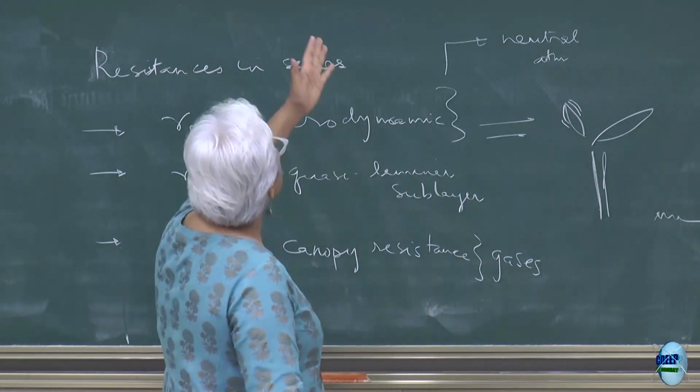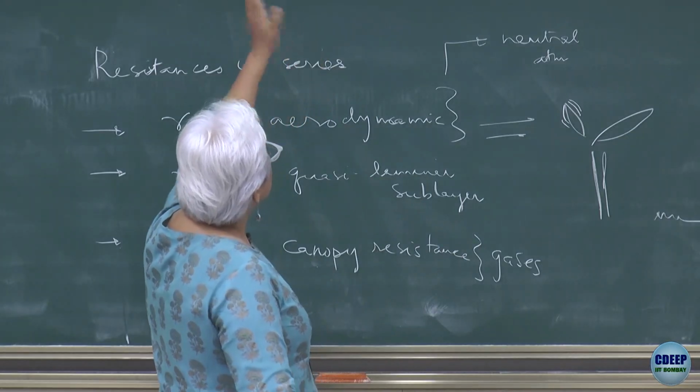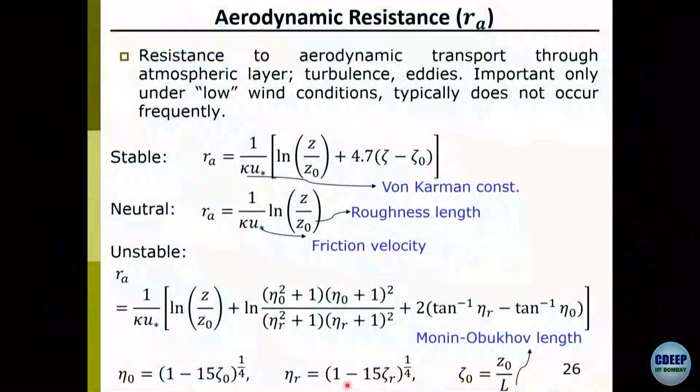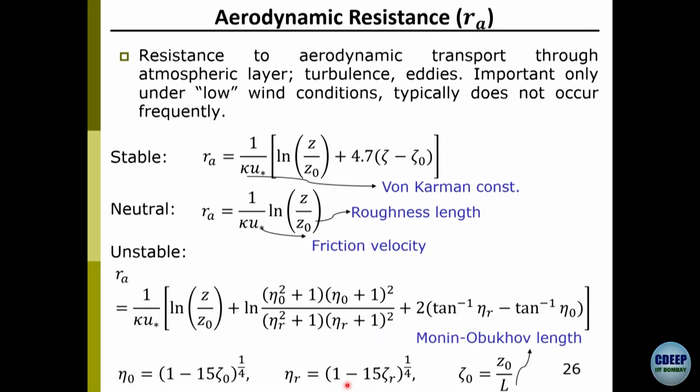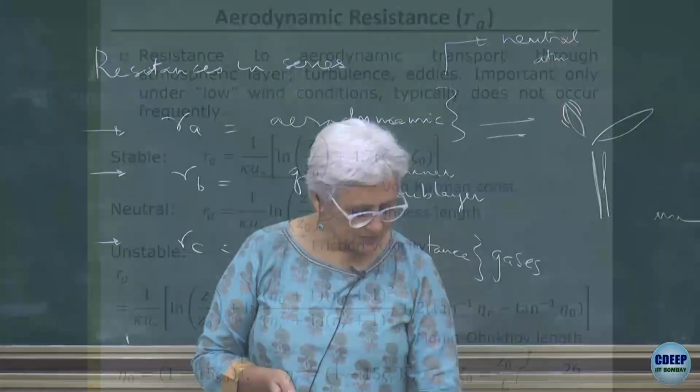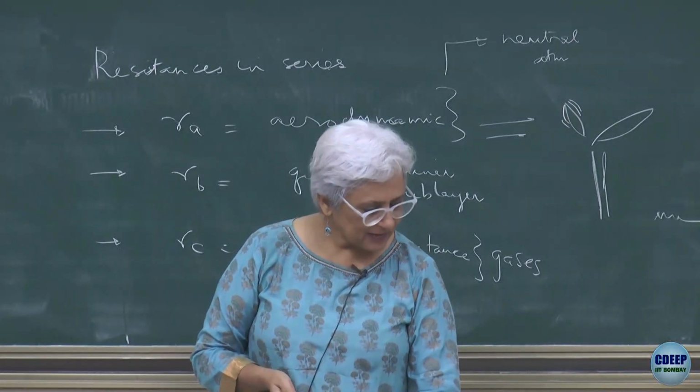So we can just quickly show you that you have that wall law appearing in the second case, for aerodynamic resistance, where you have your friction velocity, you have the von Karman constant, and that is your roughness length, right? Your roughness length, if you're talking about gravel and short grasses and so on, can be of the order of millimeters to centimeters. If you're talking about buildings and so on, you're talking about a different scale, right? So wherever your roughness lengths are.